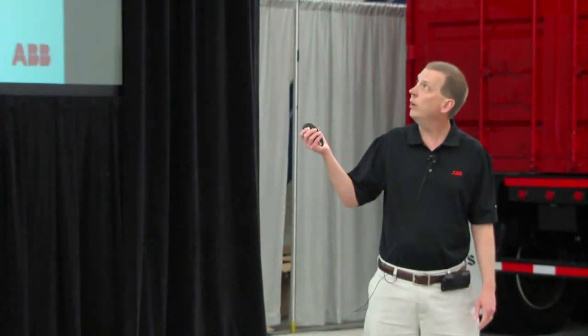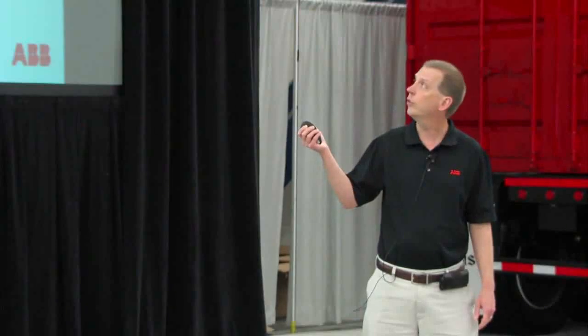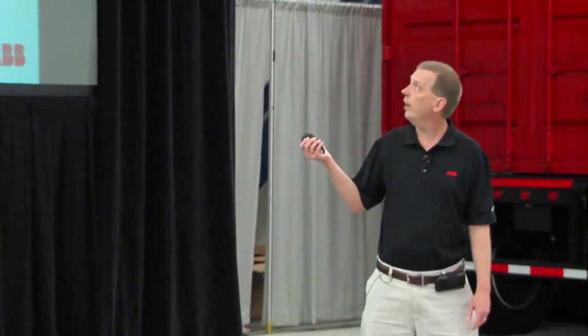And that ratio is always going to be maintained. So in an open loop scalar or volts per hertz drive, that's what you get. You get a constant volts per hertz ratio. The next thing that came around on the horizon was closed loop vector control.